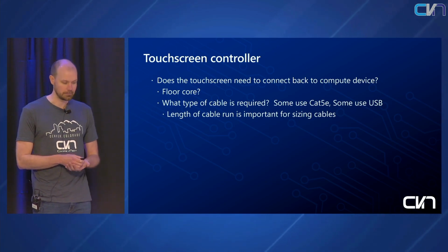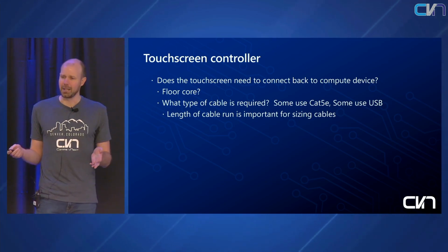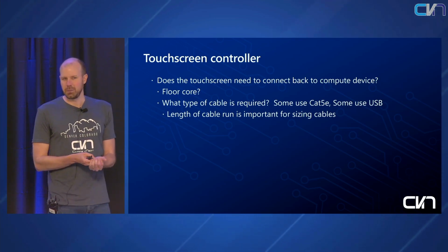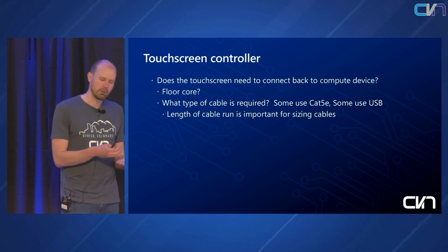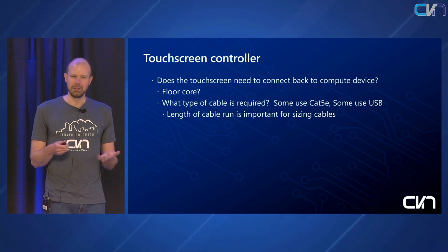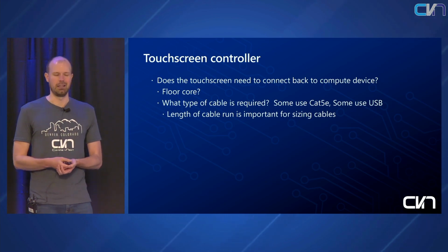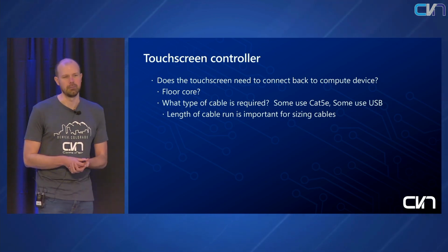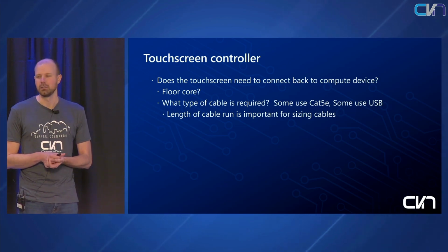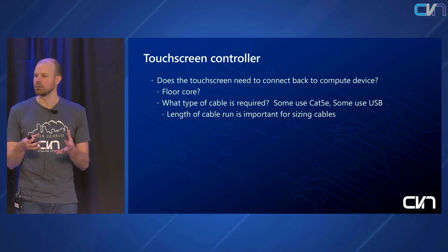That's very important. I get asked a lot about USB extenders. USB extenders, yes, they can work for USB 2.0, USB 3.0, forget it. And even the USB 2.0 extenders, I'm not really a fan of. They work sometimes, they don't. It's just another thing that can fail. So if you can get away with it, go with the more expensive USB 3.0 cable for these long distance runs.